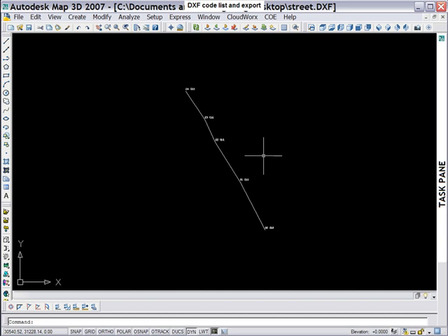So it's very nice to import DXF into AutoCAD because it brings in all the 3D line work or 2D line work. Remember, you could flatten the zeros. That just takes all the Z information and puts it at 0, so you can just bring in 2D line work. It's more flexible than FBK in certain ways. FBK, although, is very valuable, but if you're just trying to lay down some lines and want to just put them in layers, DXF export and using DXF layer names in the feature code import is the way to go.